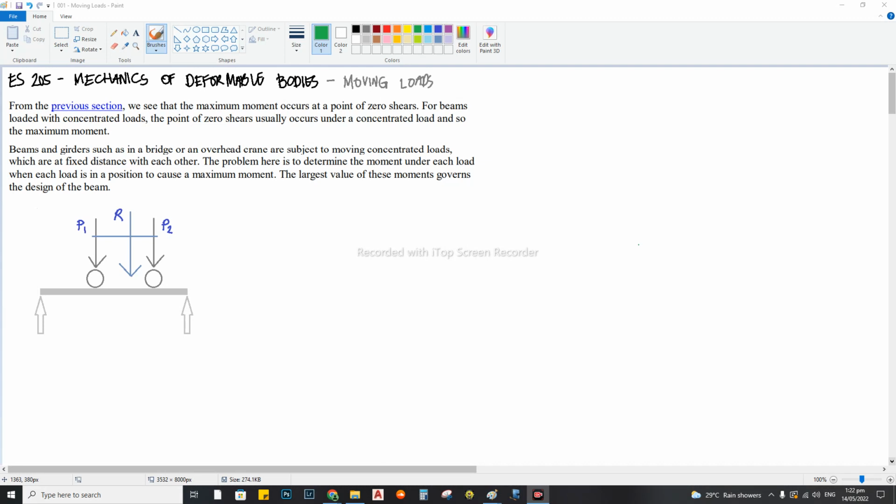we have external loads and external reactions. External loads, these are loads that were being applied on the structure. So for instance, if we have a beam, the loads we apply on it are external loads. And then external reactions, these are reactions coming from the supports of the beam. And we know that if you apply loads to any object or to any body or to any system, they experience internal reactions. We call them internal reactions or internal loadings.